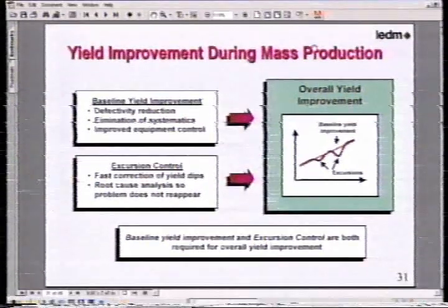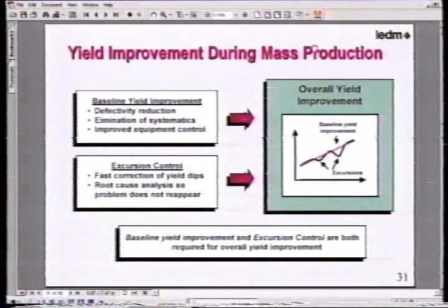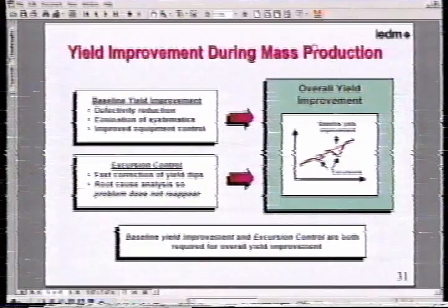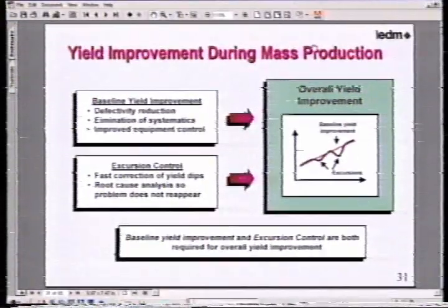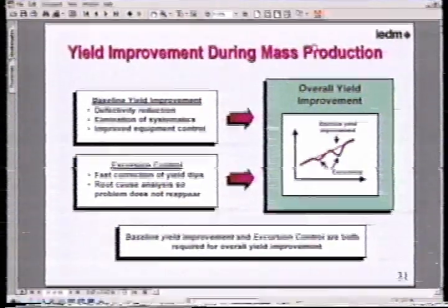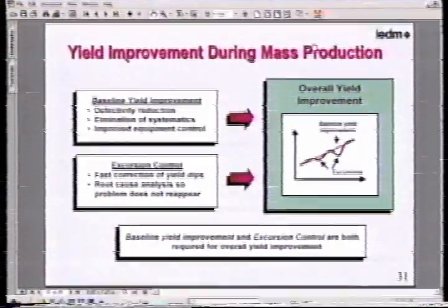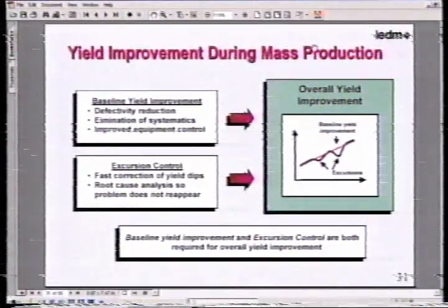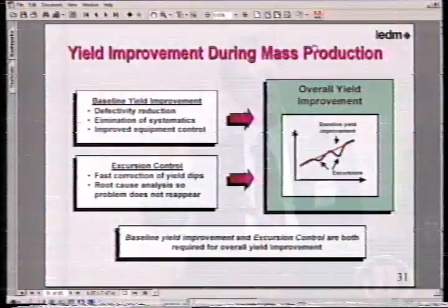I'm just going to touch on it very simply here, saying there are two kinds of things that go on when you are in production. One is just essential baseline improvement. This is where your inspection tools, what kind of scribe line structures, what kind of monitoring, and what frequency you monitor at to get statistical validity does really matter. Second thing is excursion control. And you heard about that today a little bit. Here is where your APC, understanding very quickly, getting feedback almost in line before you end your chip, before you end your product after many, many months. You figured this out from inline inspection and make sure you understand the root cause and not let these excursions happen. Because when you're in full production, this is also a killer.